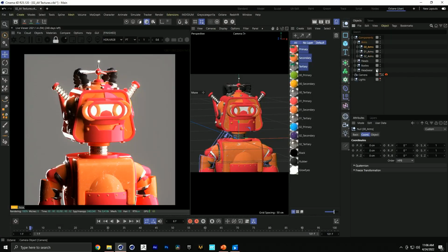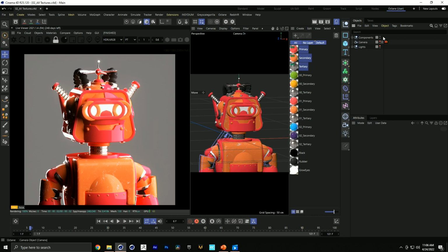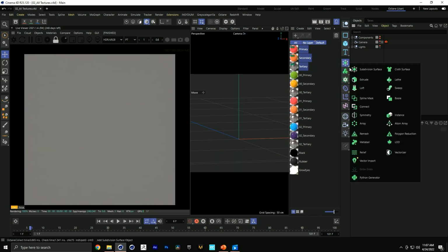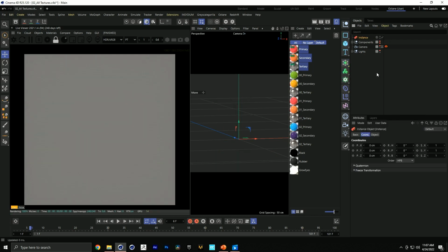And that's the case for all the arms because if you're using one instance to reference the arms and they're in different positions, it'll use the position of that instance rather than the position of the original object when referencing it. So just make sure everything is set to the same position as the other attributes in that group and you'll be golden. I'm just doing it at global 0 for position rotation because it's easier to just kind of make sure everything's at 0. So again, let's turn that off, and then we will create an instance.